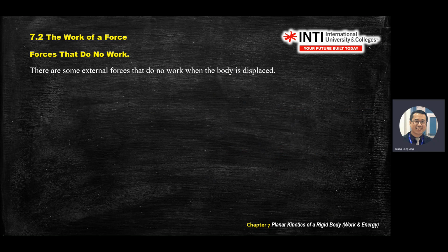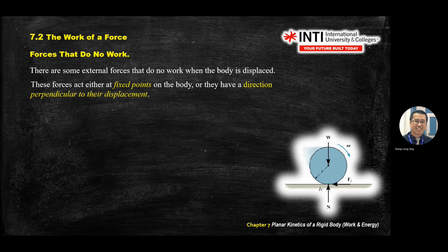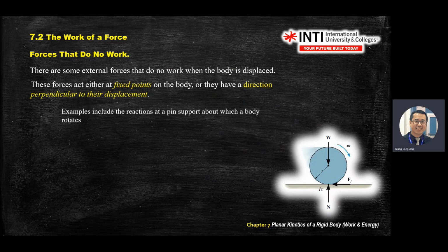There are forces that don't do work. I need to highlight this one. When your force is at a fixed point of the body, or it has a direction perpendicular to the displacement, then there is no work. Work requires the force to be parallel to the displacement. If it is perpendicular, then no work. So what are the forces that do not do work? For example, the one you see here does not do work, because it's always pointing perpendicular to the distance it travels.